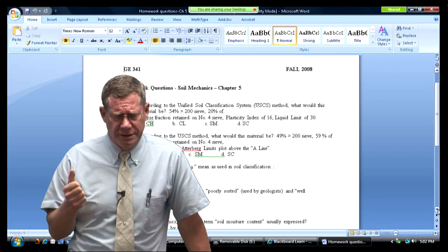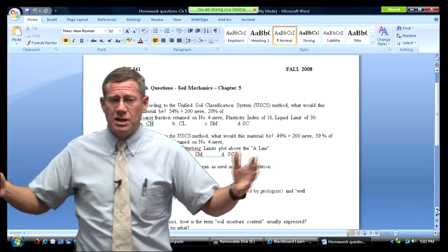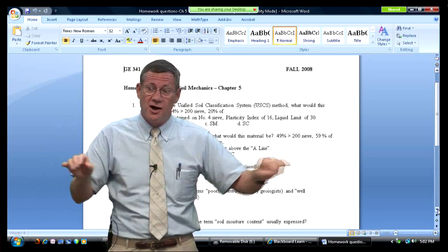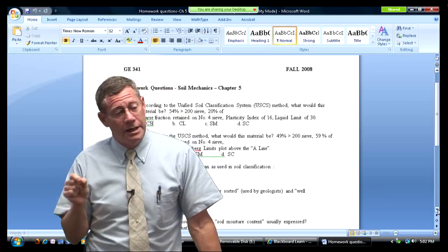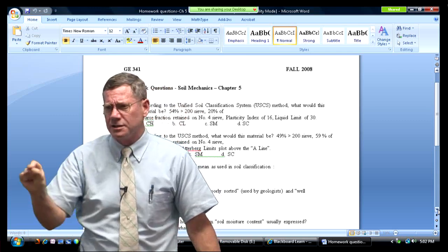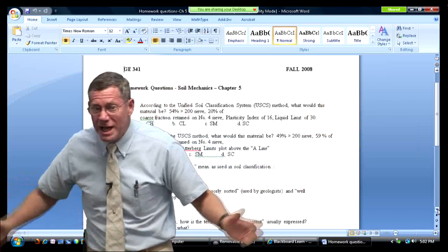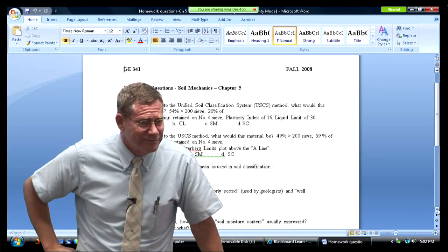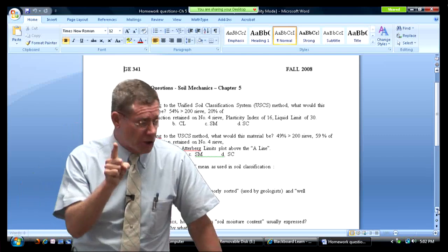Whereas well sorted in geology would mean the opposite: all one size. The only time you get poorly sorted material in geology, meaning lots of different materials, is in a debris flow. The rest of the time, it's always well sorted, all one size. And this is what's driven the Corps of Engineers nuts on doing levees all over the country. They'll come up with a specification that has a well-graded filter mixture and say, where do you get this filter material? Out here in the river. Rivers don't have well-graded material. Go out and look at them. What do they have usually? One dominant size. You want to make a well-graded mixture, you're going to have to work, W-O-R-K.